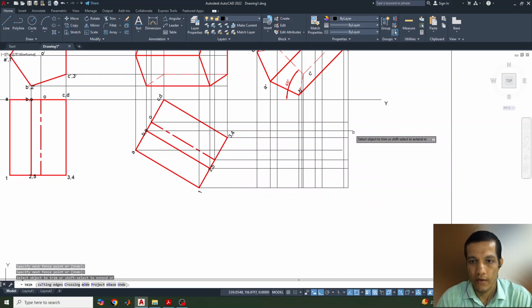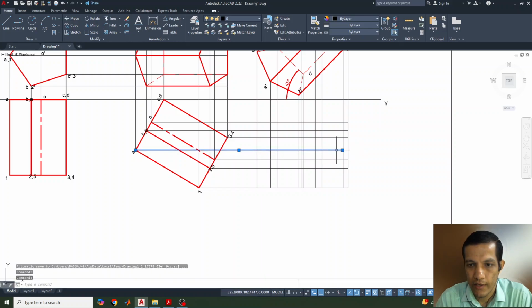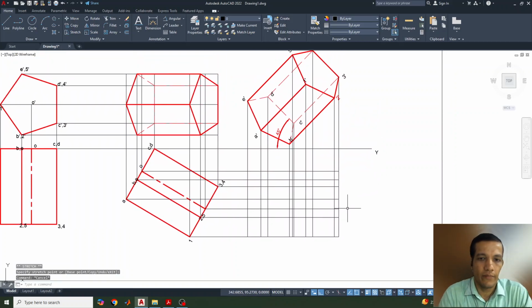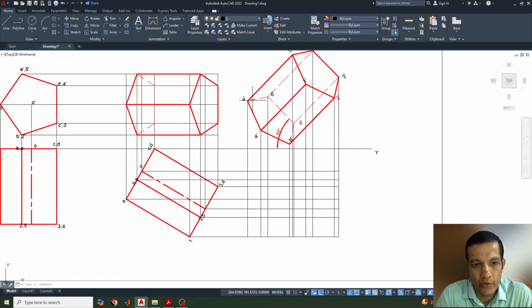Okay, and this is one line which is not joined properly here, I can join it up to the last. Now we need to draw the after edge inclination, how it looks from the top view. Again we need to go for the same thing, ABCD points we need to identify. Just change the color of this, increase the thickness, select the line. Select the A point, where it is A dash, this is the A point.